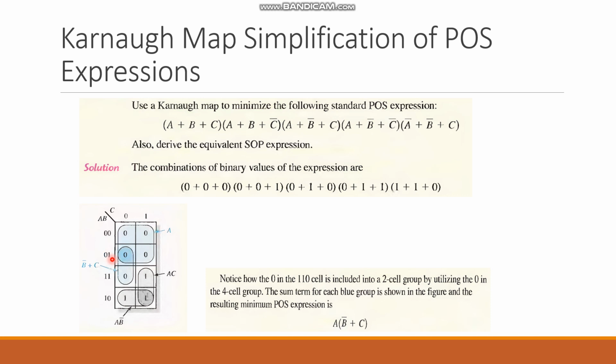So what's going to be remaining? B. But in here, where we are talking about the product of sum, we have 1, so we take the B complement because we have product of sum. And here we have 0, where C has participated with 0 only. So when it is 0, we just write down C, and we are talking about the product of sum. And then, instead of writing down B complement C, we write down B complement or C.